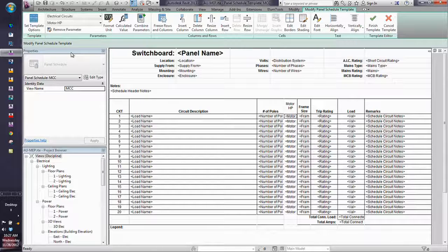So we don't have people editing the model as much. We actually have them editing a spreadsheet for the engineer or somebody else who would not be in Revit. And we've got it to where we can import spreadsheets back into Revit again and make those changes. We also do it with our SQL databases. So that's one of the ways you can get around this problem of not having them in the same circuit. But that's the only way you can get them to be assigned to a panel schedule, by going in and making sure that you have a similar parameter that you can use. It does need to be a different name. Okay? And then you've got the same values that you can go in and change.